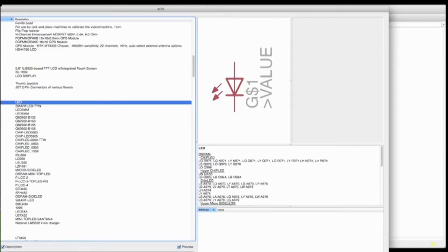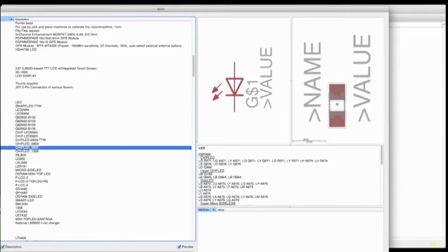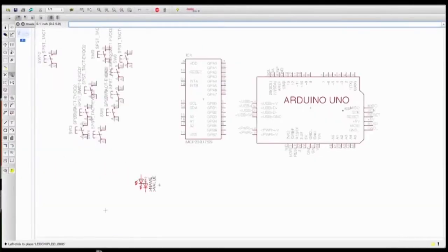So I'm going to do 0805s. I have 0603s and 0805s, but if I'm the one putting the chip on the board, 0603s are just a tiny bit small for me. So I'm going to pick the 0805s. There we go. So I need some of these, and I need 8 of these.